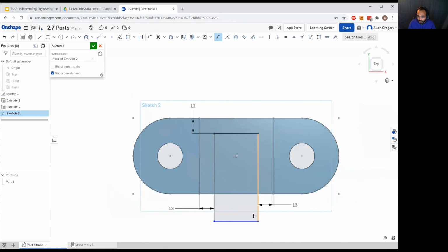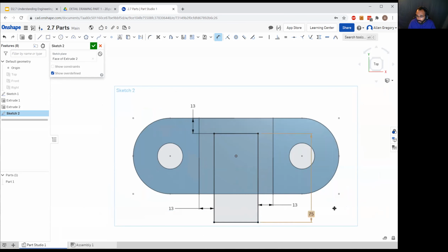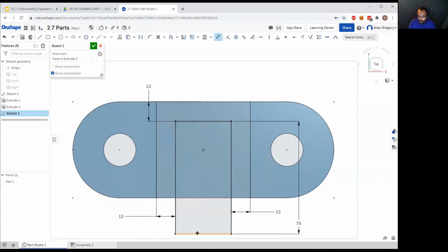All right, so now that's dimensioned. We don't have a length here, so this is still blue. If you really wanted to, you could dimension this. It doesn't really matter what that is, but it will stop somebody from moving it in the sketch and messing up our cut. So we can keep it dimensioned.